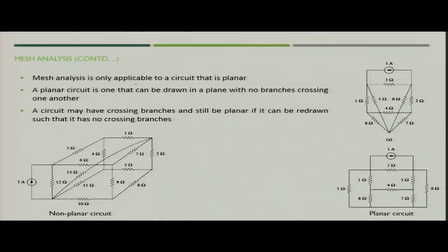Yesterday we also discussed that mesh analysis is only applicable to circuits that are planar. Planar means the circuit can be drawn on a plane and does not have any branches crossing one another. Like in this case, if you see, it is not a planar circuit because it is not drawn on a plane, it is something like a 3-dimensional structure. Similarly, here also we saw that it is crossing the branches,